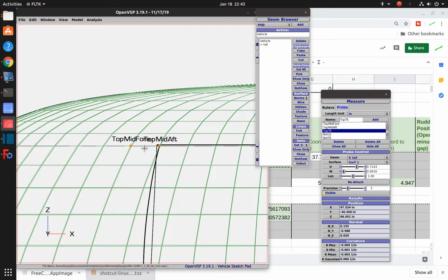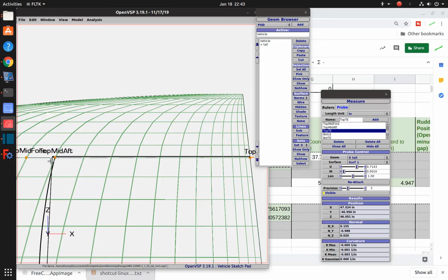When this gets exported out for our CAD import, it's going to chop our part right here along this face. I found out that some CAD programs, if you have a cut line that crosses one of these sections, especially at a very shallow angle, there are some operations in that CAD program that will not work very well across a very shallow angle across one of these cuts.